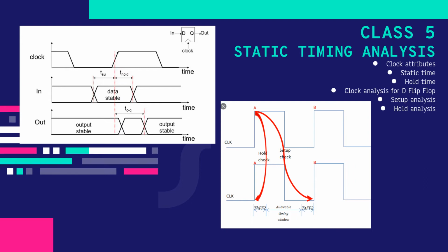We then moved on to learning the clock attributes, which are the period, the duty cycle, filter, and phase. Filter is when there should be an input when there is a rise in clock, but if there is a delay, this will be known as your filter. We then learned about setup time and hold time. Setup time is defined as the minimum amount of time before the clock's active edge that the data must be stable for it to be latched correctly, while hold time is defined as the minimum amount of time after the clock's active edge during which the data must be stable.